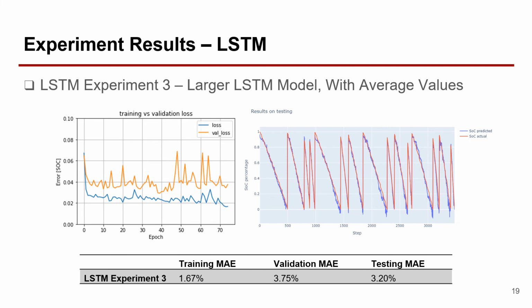The right figure shows the predicted and actual SOC plotted together over several drive cycles between 25 and -10, and compared to the previous 2 experiments, the predicted SOC values closely match actual SOC values.